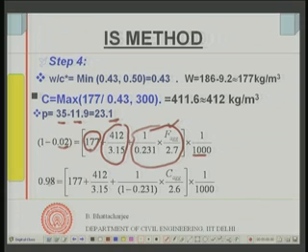Similarly, I can use a slight modification of this equation to find out the volume of the coarse aggregate, and here the coarse aggregate mass comes into the picture divided by 2.6 and the volume fraction of the coarse aggregate, which is 1 minus 0.231, because this is the volume fraction of fine aggregate in the mix.